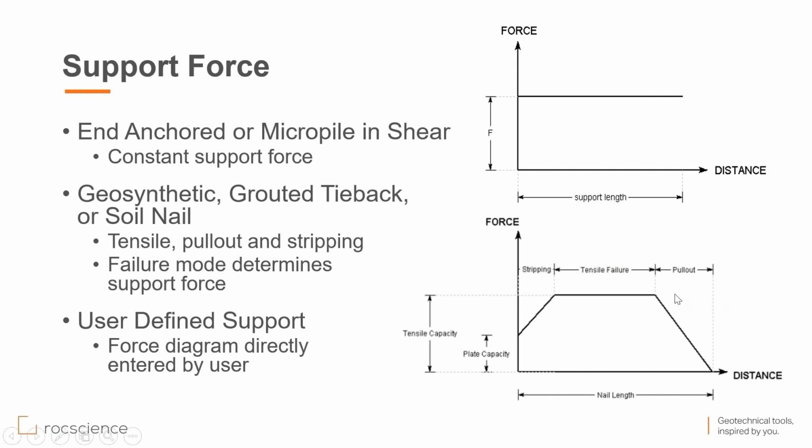So if this is a support, for example, it might turn out that the lowest is the stripping force for this part, tensile for the middle part, and pullout for the latter part. And when you use a user-defined support, basically you're just inputting your own support force diagram.